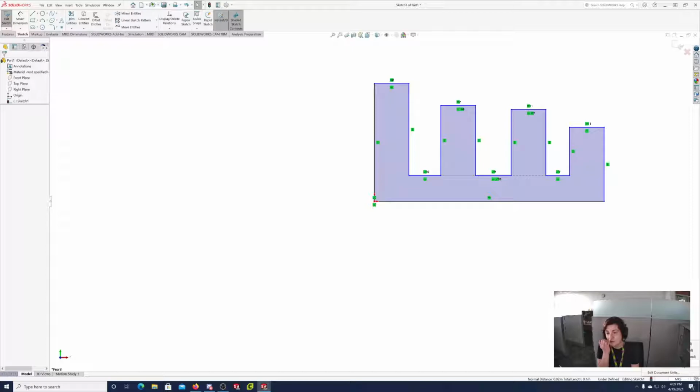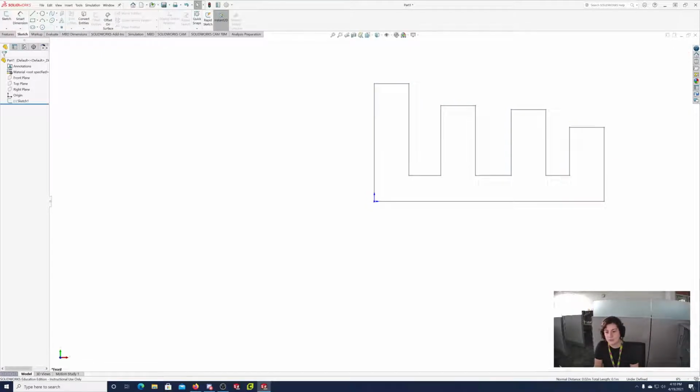If you're drawing something in meters, and you meant to do it in inches, it's going to come out way bigger than you wanted. So you've got to be really careful, because after you've modeled an entire part, it's a lot harder to scale it to the dimensions you want than it is to just start with the right units of measurement in the first place. So we want IPS, so let's make sure we select that before we start dimensioning.